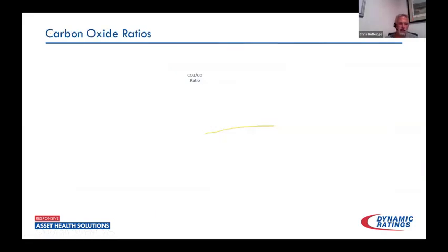So just a little more backstory on this. These transformers both tripped out. As with most trip outs, some more investigative testing was done. It was sent out, and power factor tests were ordered for both transformers. Both transformers tripped the test set out, couldn't get current on it. So we're seeing open winding, which of course with the burnt lead, yeah, we do have an open circuit there.